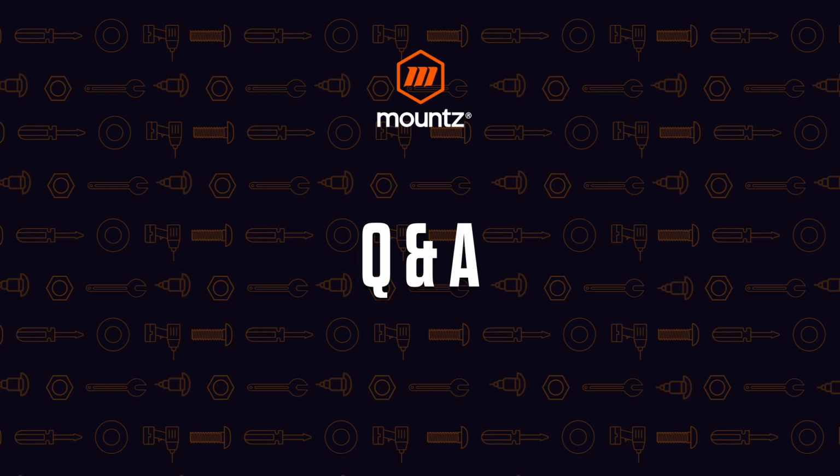All right, Dave. Another question we had is, for testing or calibrating a tool that's not a power tool, like a hand tool, is it a good idea to use a rundown adapter or not? Typically, you don't need to do that when testing a hand tool because there's not as much inertia being generated by the actual tool when it shuts off, like a power tool would. So using a hand tool directly on a sensor is not going to be an issue.